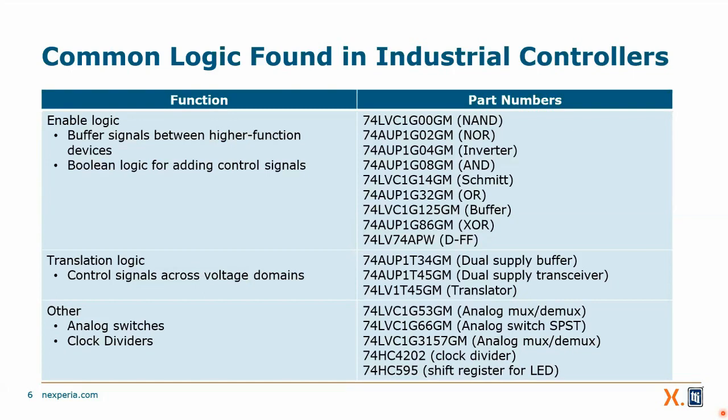So each year, more and more translator devices are being designed and being used because these controllers are stretching over many years. You want to keep using the 5 volt controller you designed 20 years ago because it really works well. You have to hook it to your sub 1 volt microprocessor. So you have to look at those things, and that's why these translators are becoming more and more popular.